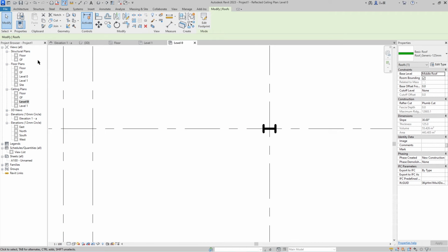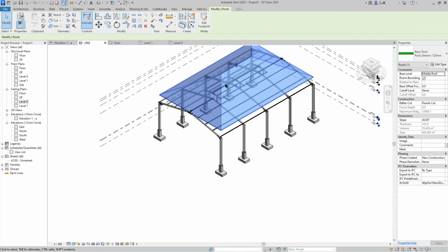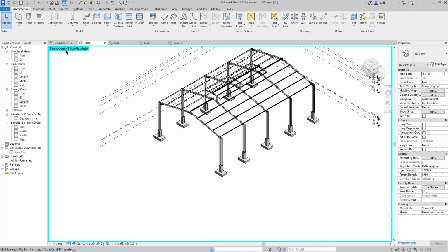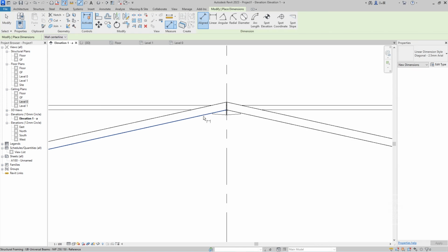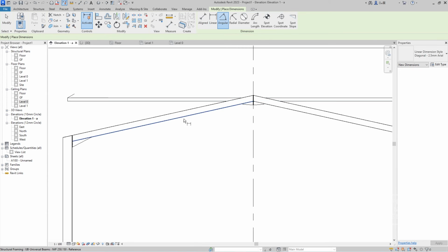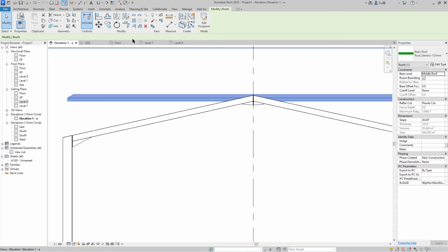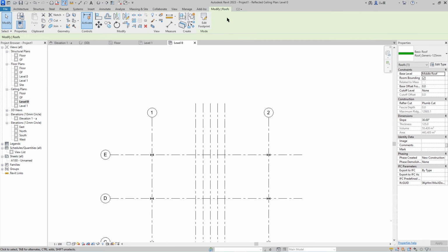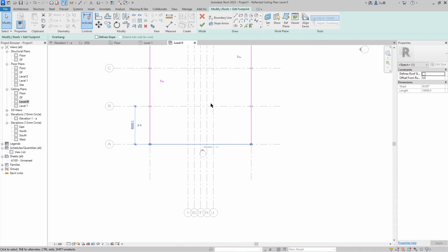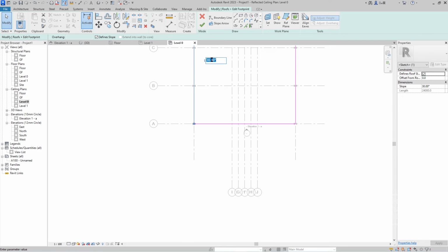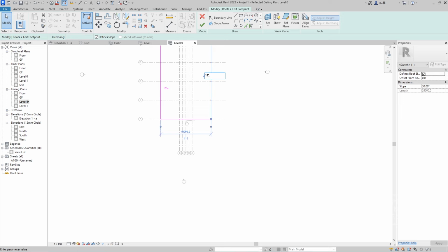But maybe this is going to be a very bad roof, but it's okay, no problem. Let me just hide everything firstly, and let me go to elevation view. I'm forgetting something here. Let me go to dimension by typing DI and choose the angular and choose this one to this one. This will be 12.48. So all we need is to just modify this roof and go to the just one, and let me turn off this one because we don't need this one as roof slope, and then this one, and let me use this one as 24 times 40x, and similar with this black 1x.